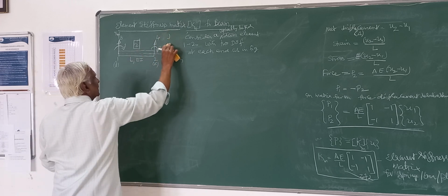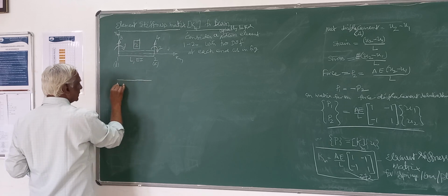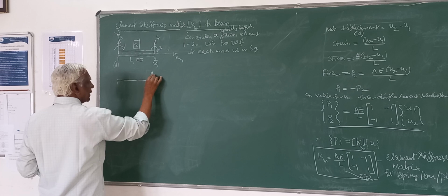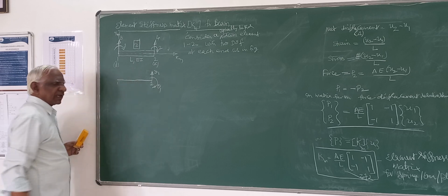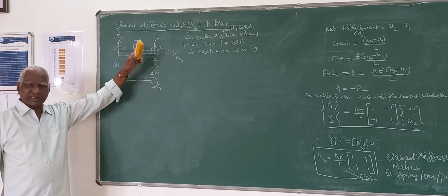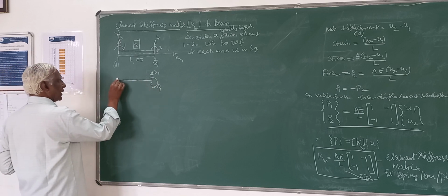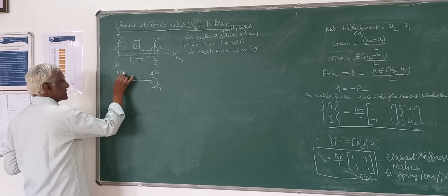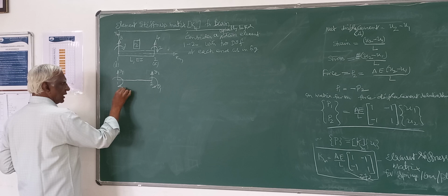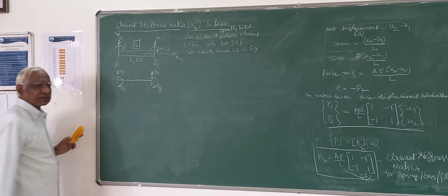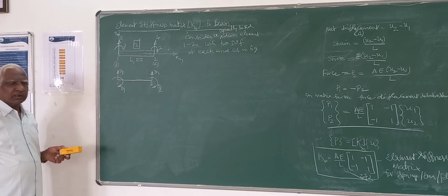This is indicated by another sketch. 1, 2, the displacements V1. Always I will take the positive direction of vertical displacement in the vertical direction and of rotation clockwise, always positive, which I told already. The notation is to be considered. Here it is V1, here it is theta 1, this is theta 2. So these are the unknown displacements.